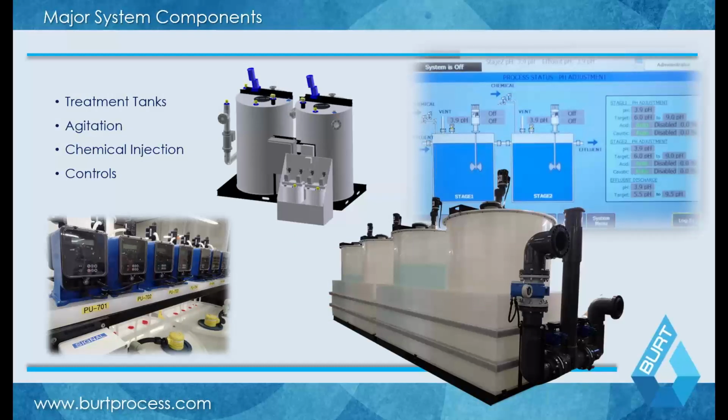Regardless of the type of system you utilize, whether you use a flow through, a batch, or a hybrid system, all pH neutralization systems have certain components in common. Treatment tanks, they have agitation, they have chemical injection, they have controls, and then they typically have some form of effluent monitoring attached to them.